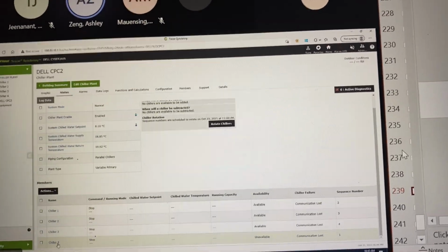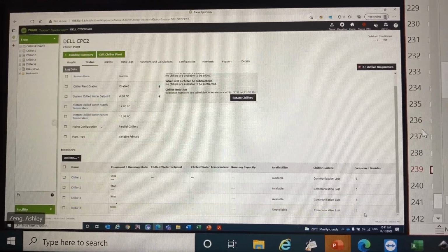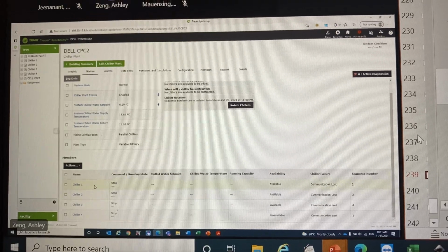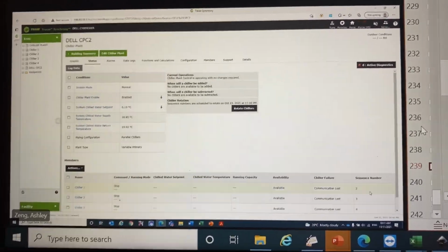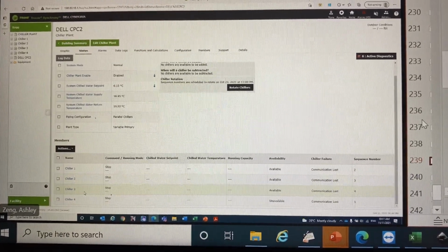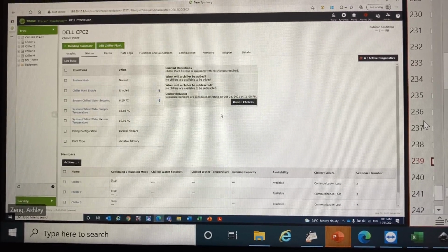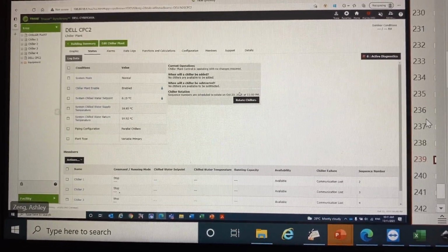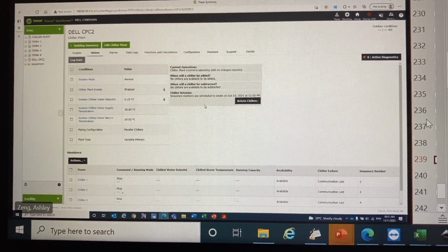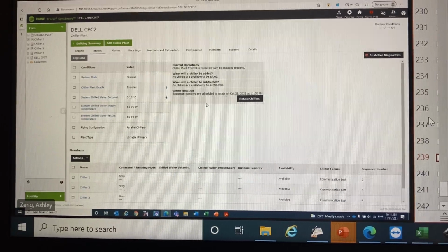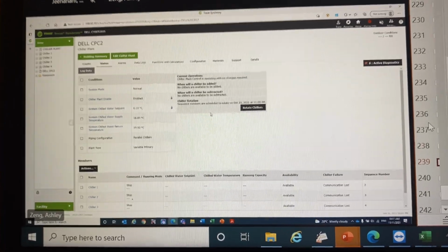Just now we changed chiller 4 to sequence number 1. Remember, just now we did a rotation, and chiller 1 became sequence number 2, followed by chiller 2, lastly chiller 3. So sequence number will not be according to their name. It will always rotate based on the rotate conditions that you have. You can also tie this chiller sequence rotation point to a time schedule such that it can be rotated on a weekly basis, or every couple of days. It depends on your requirement.